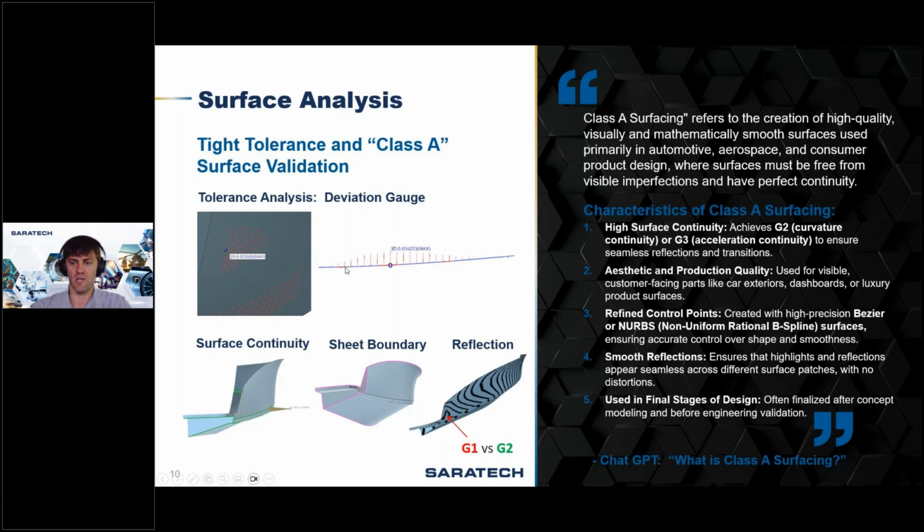These things operate in real time. As I constructed this curve on this particular project, I could change those curve parameters and watch the deviation adjust in real time. I was able to get this dialed in pretty close. Same thing on a surface. As I rebuild those surfaces and redefine them, I can see where my max deviation is and how it's deviating. Those are very powerful tools for developing either reverse engineered or Class A surfaces.